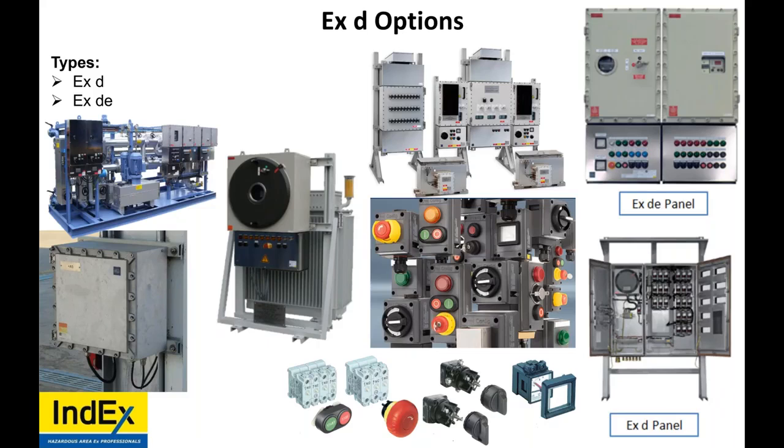Okay. Thank you for your questions, guys. I'm just going through. We're having explosion proof only in joints or other joints. So explosion proof has 4 different joint types: threaded, spigot, flange, and also the labyrinth for rotating equipment.